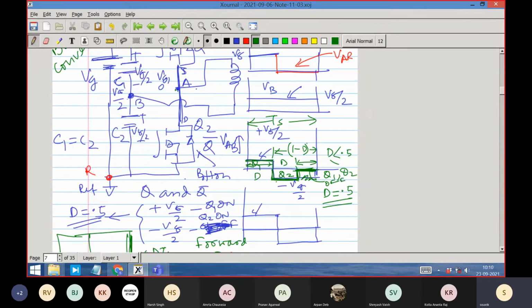That will make that node go to that voltage; the voltage across the transformer will be 0, imposed on the secondary side. When you are making Q1 and Q2 off, the voltage imposed from the secondary side of the transformer will be 0. Therefore, being a coupled side, the primary side of the transformer will be 0. So that is what we will show you now, right?